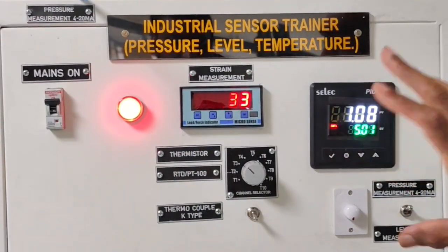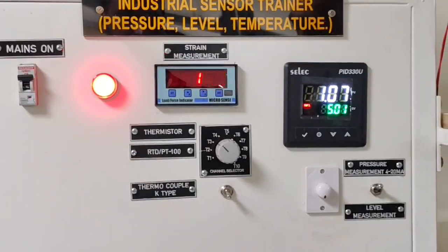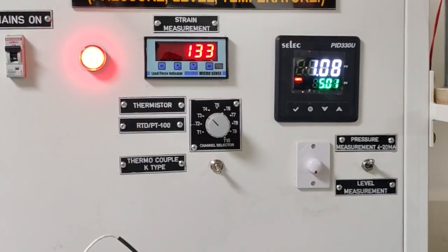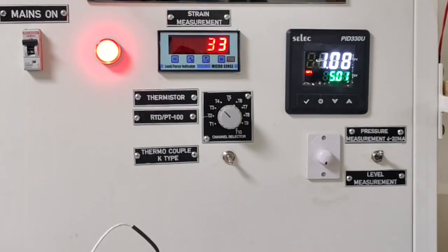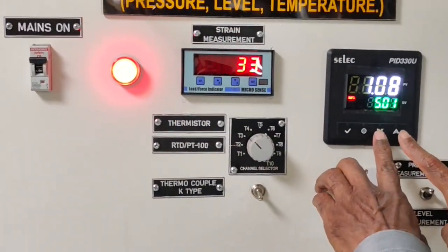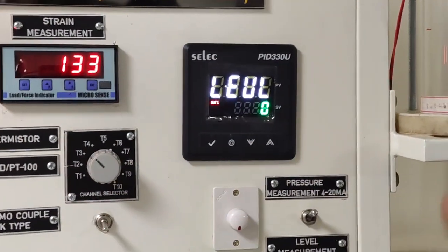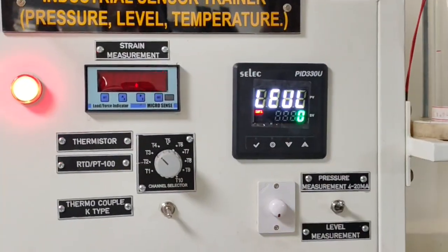PIDs have different programming systems. Only level 0 is related to you. Level 1, level 3, level 4, all those things, automation, are there. One PID controls entire instrument equipment in the industry. For that reason, these two are the up and down. How to enter the level? You just have to lightly press it. It will show level 0. Once you come to level 0, it will hold for 30 minutes. If you don't program within 30 minutes, again it goes back to square one.